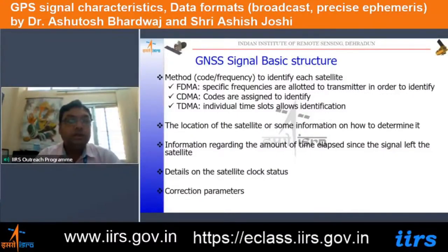Once the concept of GNSS came in 2006, GLONASS also started giving CDMA codes. Thereafter only, the concept of GNSS actually got fructified. The same receiver can receive the signals from GPS and GLONASS as CDMA codes, and it can resolve the position. So even if two signals from GLONASS and two from GPS are available, the position can be resolved.